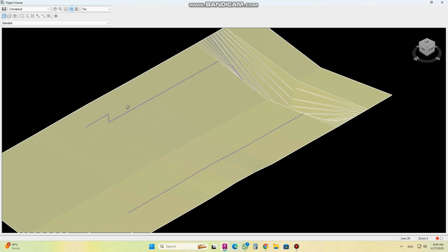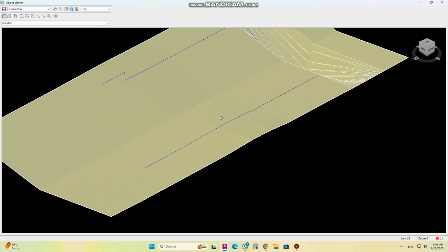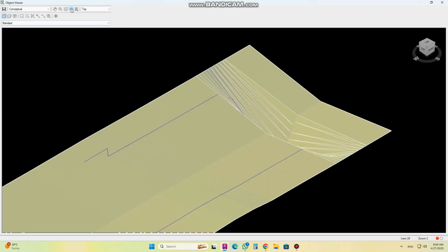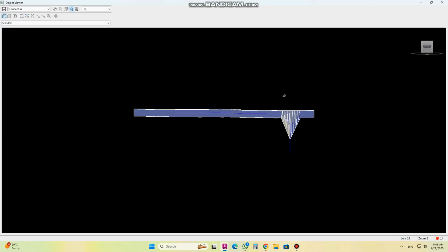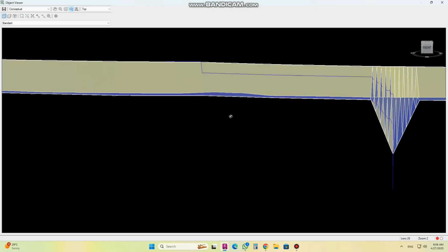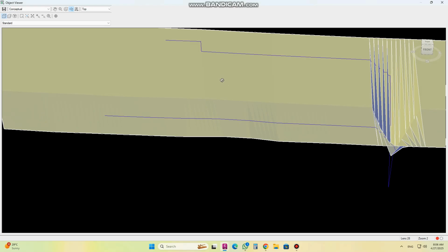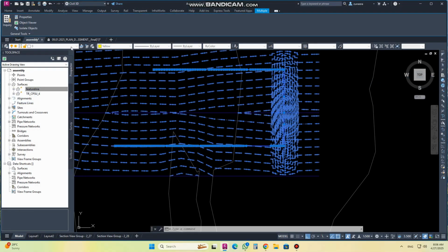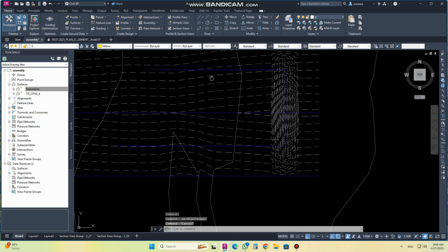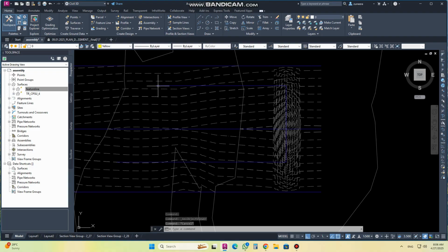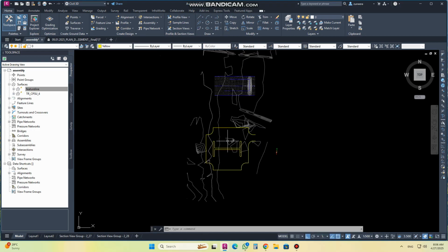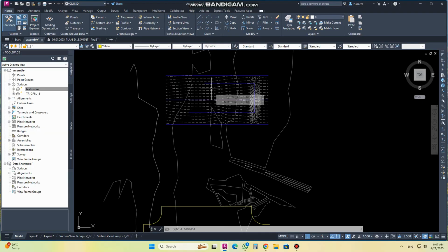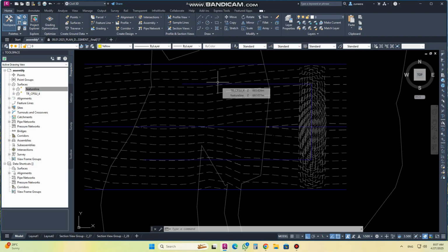The first portion is exactly laying on the surface here. The next is going up to the surface because I moved downside. But the main thing here is, if you select one portion as absolute, it will not move, and the relative to surface will move up and down from that part. Okay, so that was a little bit about the behavior of the feature line.